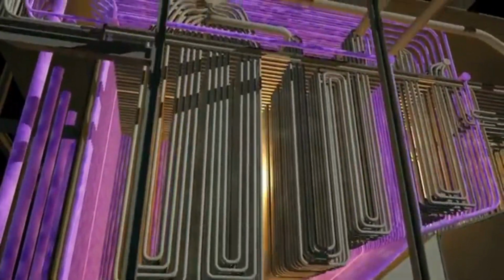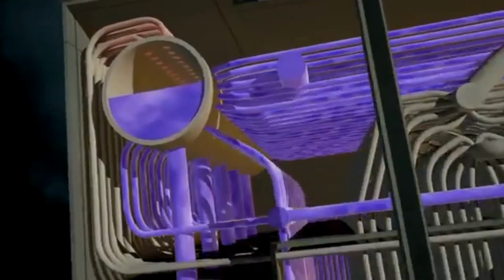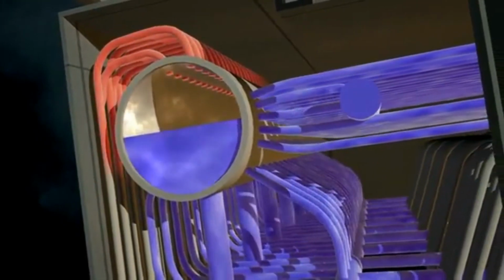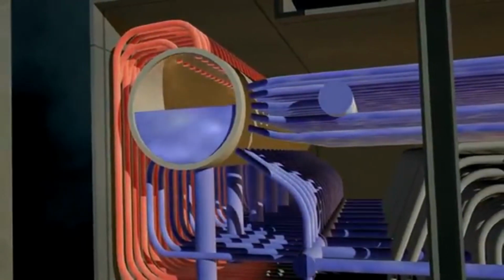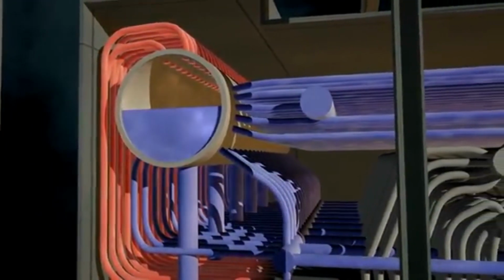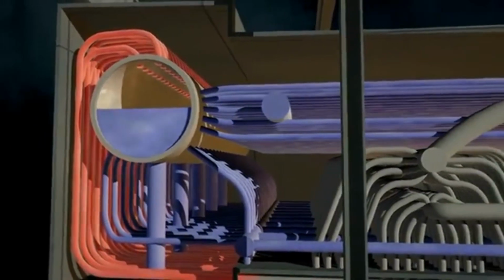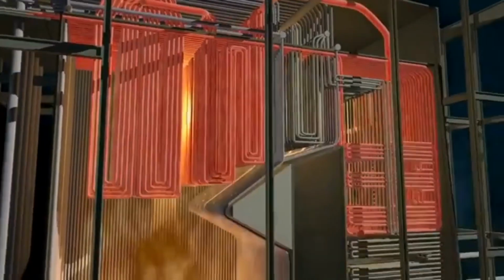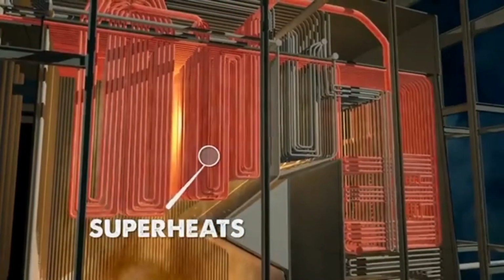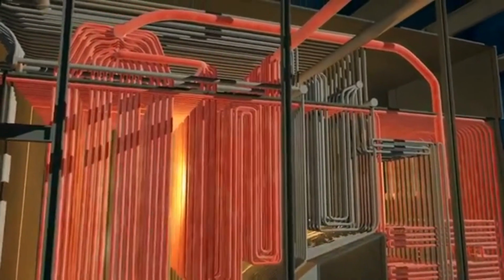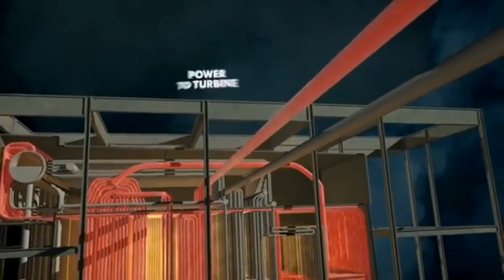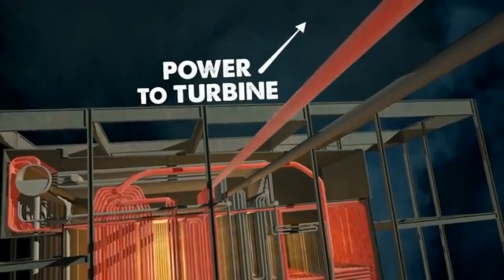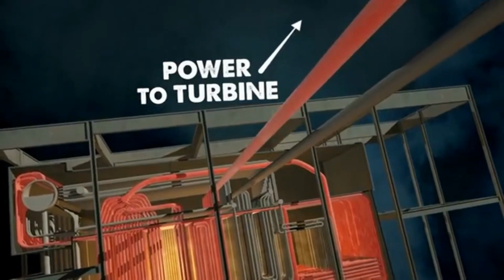Liquid water flows through large downcomers and into the base of the firebox, a network of 2-inch tubes in the firebox walls, and burners continuously feed combustible fuel into the ultra-hot firebox. Eventually, the inside of the firebox burns so hot that its surrounding steel walls would melt.